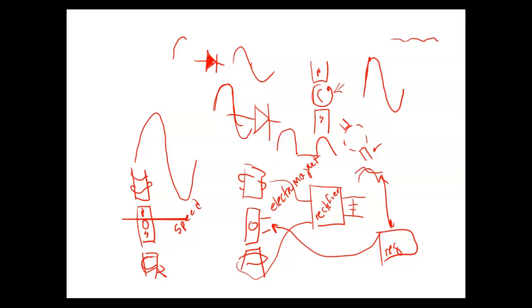These AC tach generators will basically last forever unless you physically do something to break them. So AC tach generators are cheaper. They're more reliable. They last longer. DC generators are still out there, but usually in older ones, because once we got the ability to take AC and turn it into DC using rectifiers, DC tach generators just are not used that much anymore.